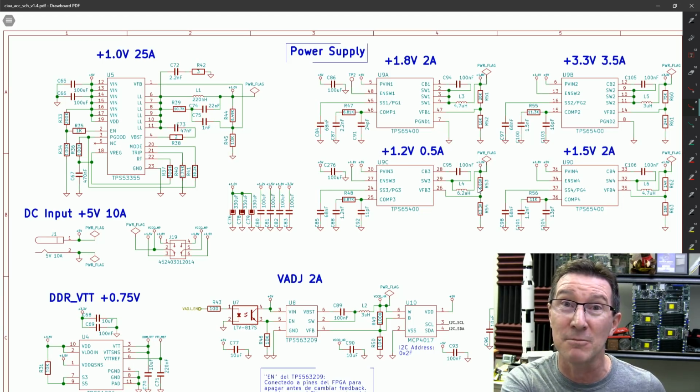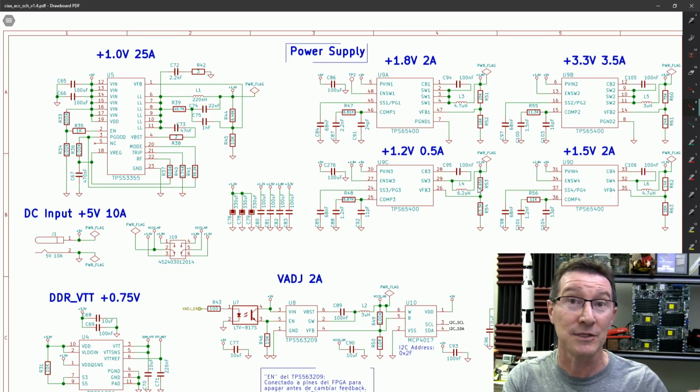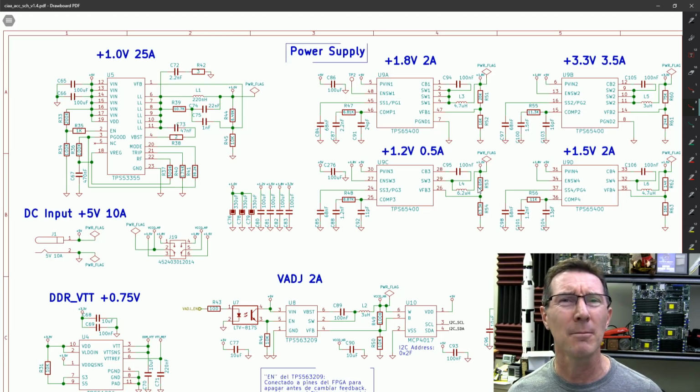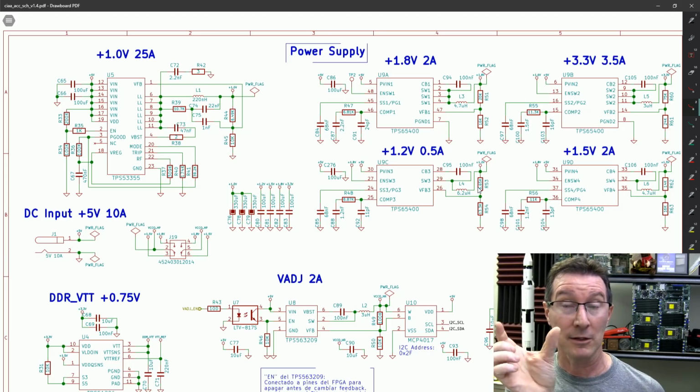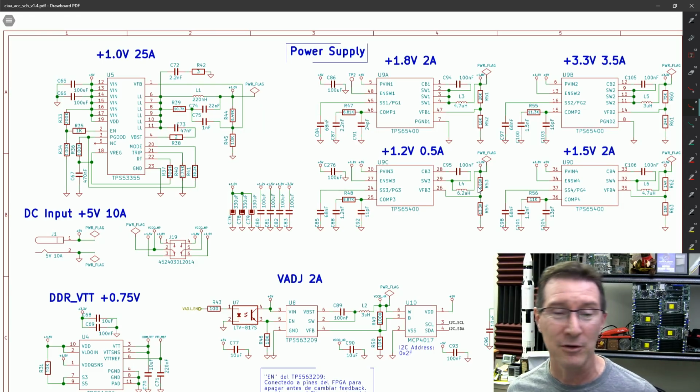You might even do some Monte Carlo analysis in simulation. Have I done a video on that? I think I might have. It's where you can test your design for a spread in your values, like 5% or 1% tolerance resistors. It'll go plus or minus 1% and rerun the simulation and tell you if it's going to go wrong on you, and things like that.